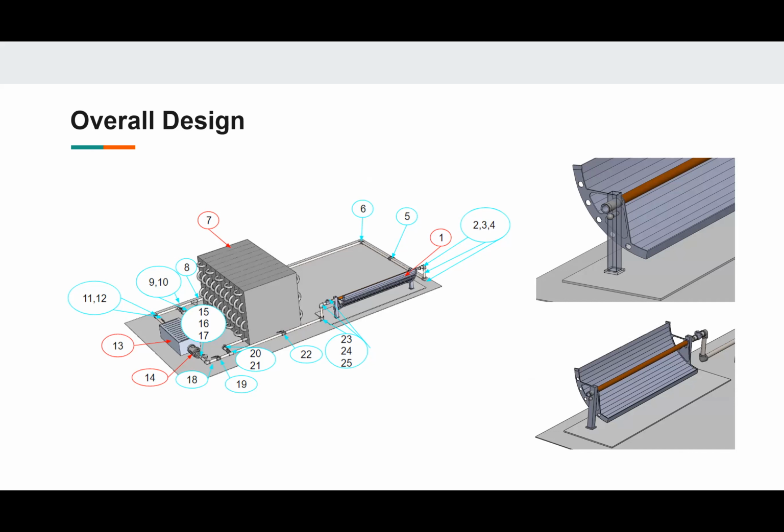The overall design requirements were intended to provide a good amount of serviceability as well as functionality. Hence, this design uses 6 ball valves at points 5, 10, 20, 19, as well as 22. This makes sure that anywhere throughout our pump and pipe system, we're able to restrict flow at any point, and that they're accessible at all areas of the overall footprint, so if something catastrophic happened, we're able to shut it down quickly.